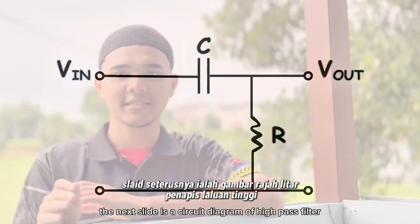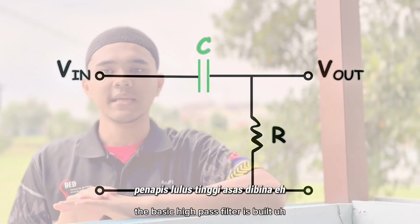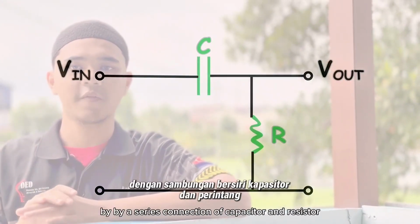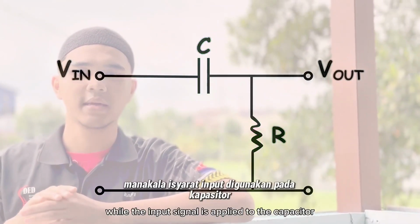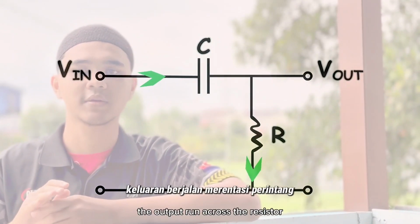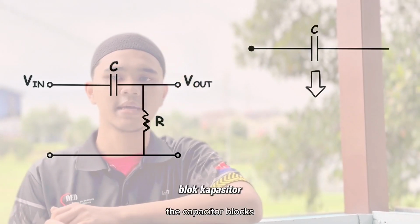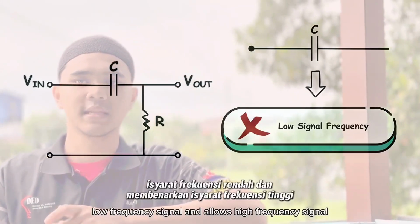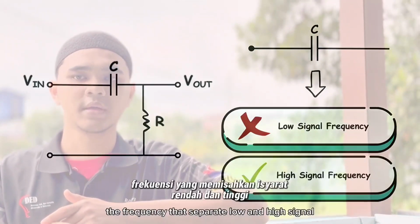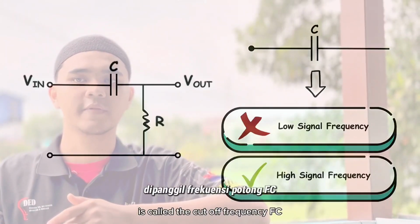Okay, the next slide is the circuit diagram of a high pass filter. The basic high pass filter is built by a series connection of a capacitor and a resistor. While the input signal is applied to the capacitor, the output is taken across the resistor. In a high pass filter, the capacitor blocks low frequency signals and allows high frequency signals to pass to the output. The frequency that separates low and high signals is called the cut-off frequency, Fc.